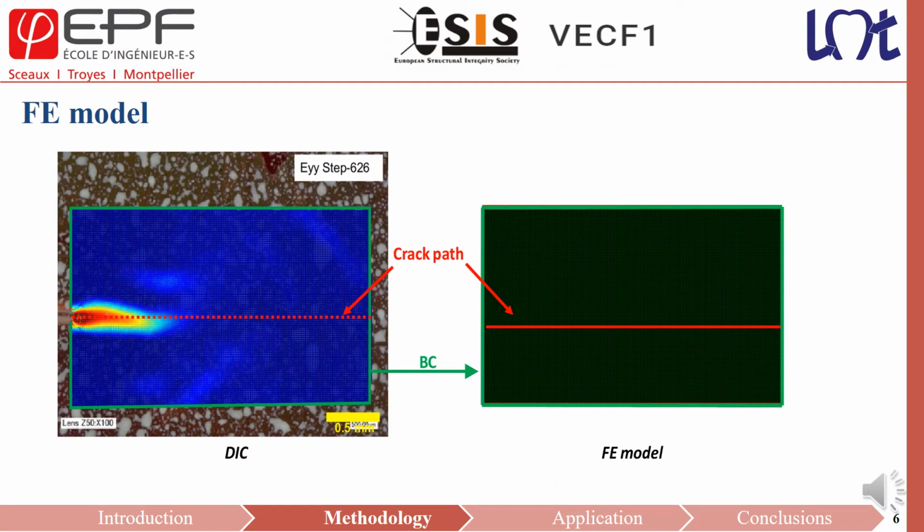In the finite element model, the DIC region of interest was modeled as a 2D rectangular area meshed with 4 node planar stress elements. The mesh size is the distance between consecutive subset centers. In this way, the number of nodes in this model was identical to the number of DIC subsets. Boundary conditions were defined by prescribing the displacement of the external boundary of the region of interest.